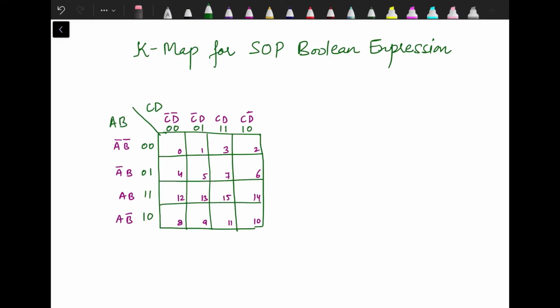We have also seen that we can make the groups of the adjacent zeros or ones depending upon whether we are given the minterms or the maxterms respectively. They can be combined in groups of 2, 4 or 8 resulting in a pair, quad or octet.